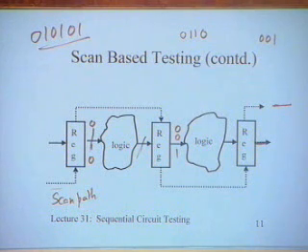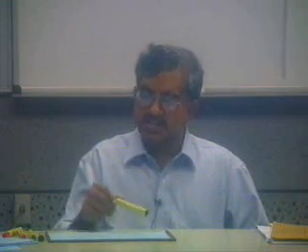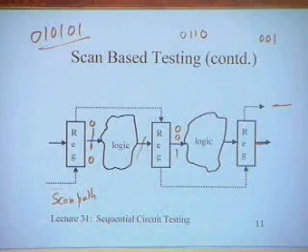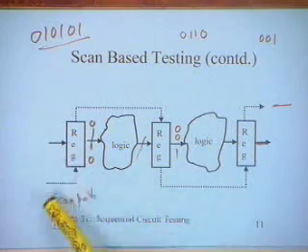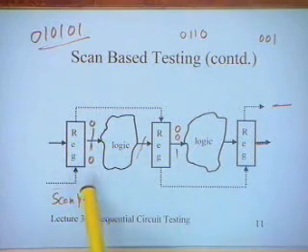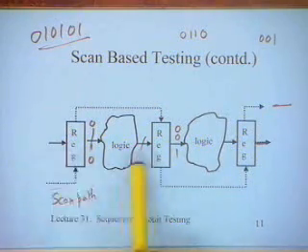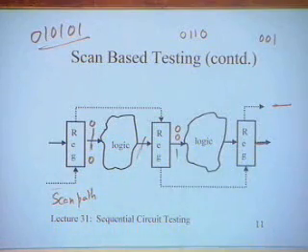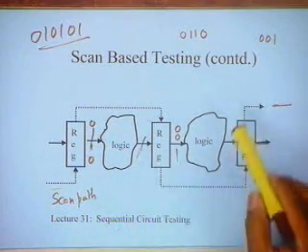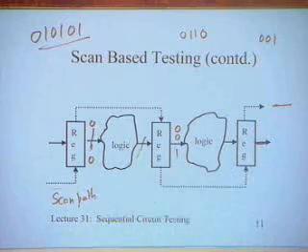There are certain drawbacks here, one should also be aware of it. Apart from the fact that if you have a lot of test vectors, the time to test is going to be fairly large, because each time you push the test vector to the proper register or set of flip-flops, then get the output, and then read the result, it is going to take time. Some overlaps are possible but only limited. So that's going to take time.